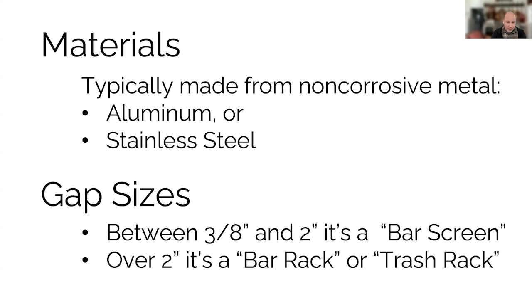Something really important to remember is that bar screens have to be cleaned periodically, typically at least daily, quite often more often than that, hence the mechanical options. The size of the screens and racks really depends on the size of the channel that they're in. So a small setup could only be a couple of feet across, whereas a very large installation could have multiple bar racks or bar screens that are 10 feet or more across.